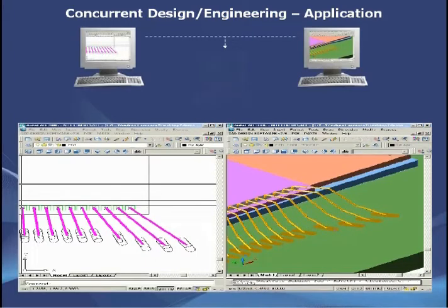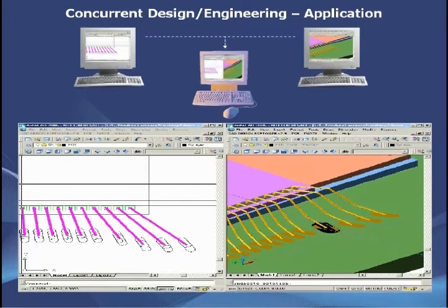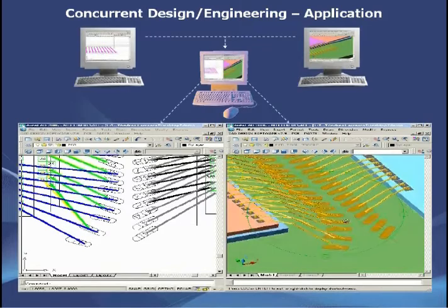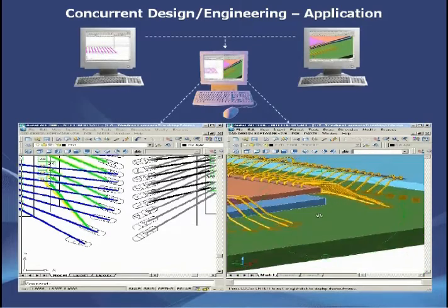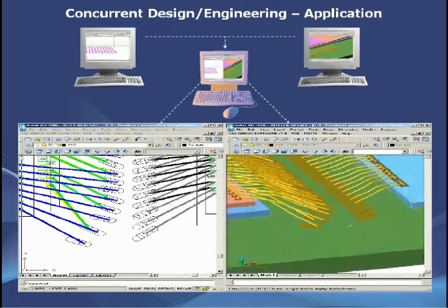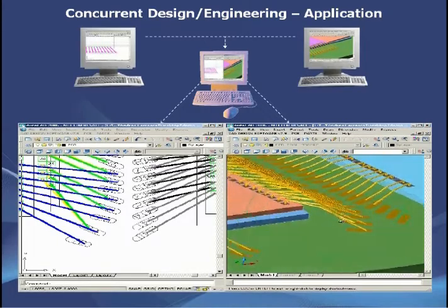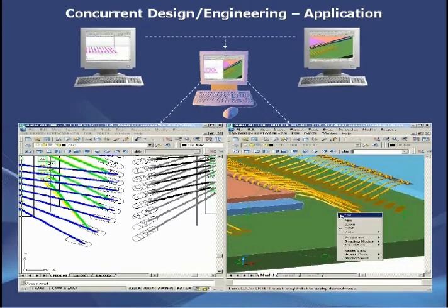On one of the user's PCs, or on a separate PC, for example a manager, two connections are built. As the wire bond engineer moves a substrate bond finger in the 3D environment, the cockpit program dynamically connects to the engineering CAD applications and the database, and in real time updates the wire bond fan-out in the 2D environment.